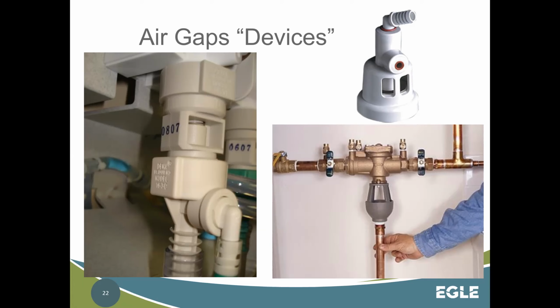And it's a chemical mixer thing. If you open the front of it, you will often see these air gap devices like these two here, this one and this one. You have your chemical line coming in, the water line comes from the top, but there's an air gap here physically that separates them so that they don't ever backflow into the water. All right. Bob will talk about that stuff tomorrow, or you'll see more pictures of him tomorrow.